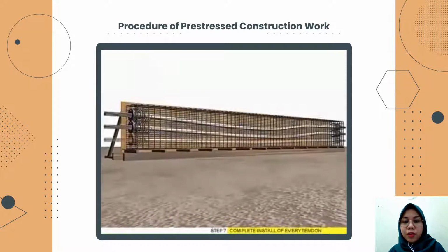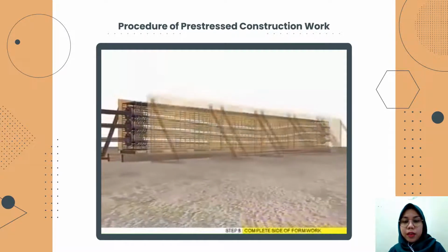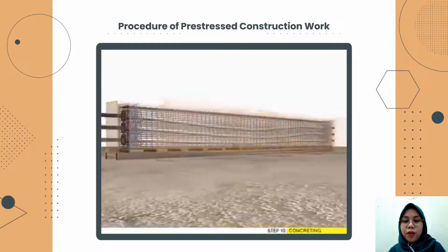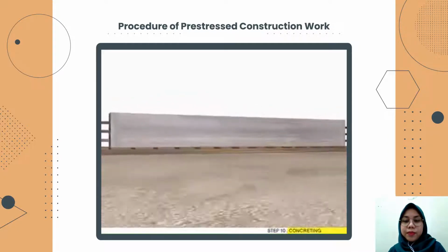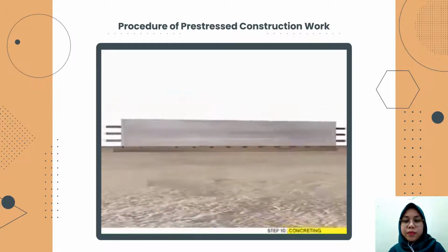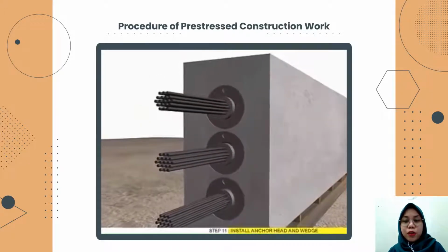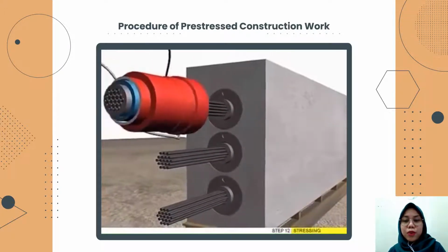7. Complete installation of every tendon. 8. Complete side formwork. 9. Complete end formwork. 10. Concreting. 11. Install anchor head and wedge. 12. Stressing.